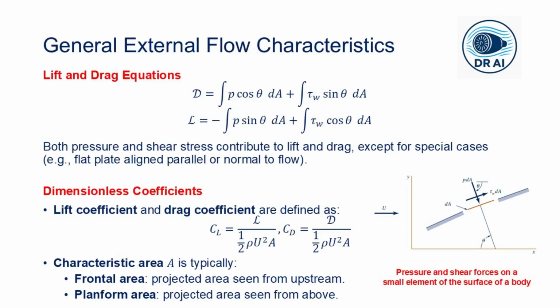So let us get mathematical for a moment. Don't tune out. This is important. For a small area element dA on the surface, oriented at some angle theta, we can break the forces into components like the x component, which is the drag direction, and the y component, which is the lift direction. So we write the particular equations as represented over here. Then we integrate over the entire surface, and we get the drag and the lift forces like these.